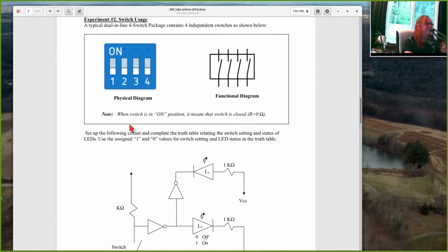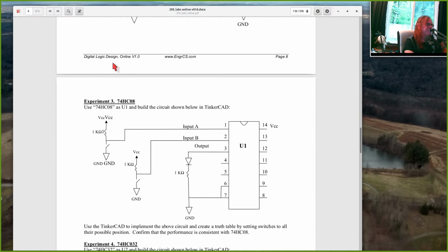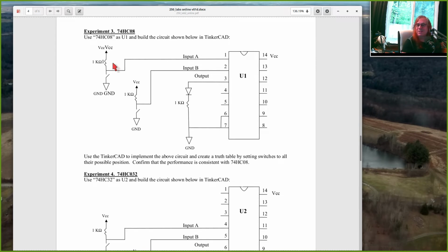The slightly odd thing is if you put your switch in this orientation, when you slide this little piece of plastic up to where it says on, that's a logic 0. And you know, light switches in most houses, when you flip them up, the light turns on. We think of that as the direction where things happen, right? So if you want that up position to mean logic 1, just take this block and flip it over 180 degrees on your protoboard so that on is on the bottom. And now in this position where all of these switches were down, the output would be logic 0, and when you flip the switch up, it would be logic 1. But whichever way makes sense to you, that's fine, right?